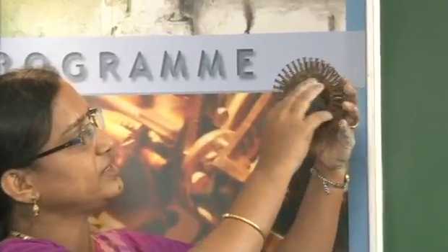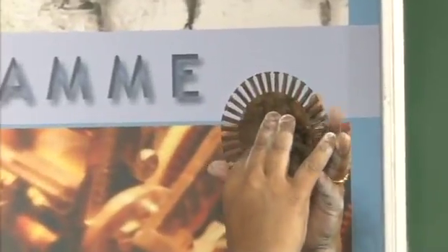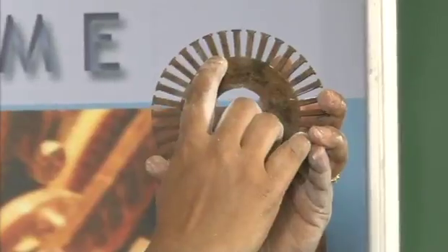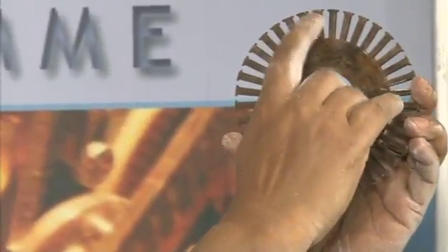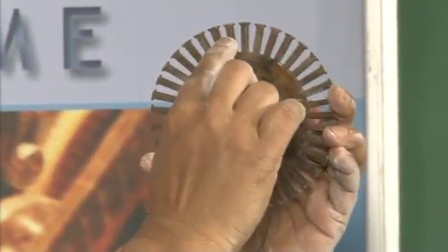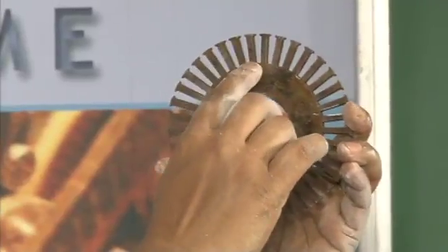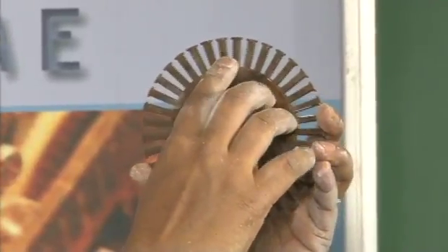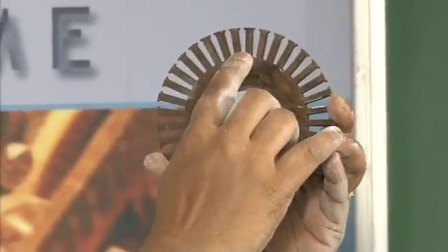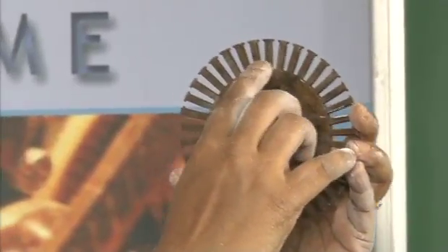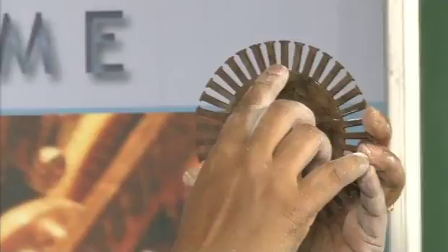You see that here it is slotted in the outer periphery. Okay. So now in this problem you have to find out how many conductors are placed in this slot. The calculated total number of conductors is 750. So now the number of conductors divided by the number of slots given, that is 150. 750 divided by 150, the number of conductors you can place in each slot is 5.